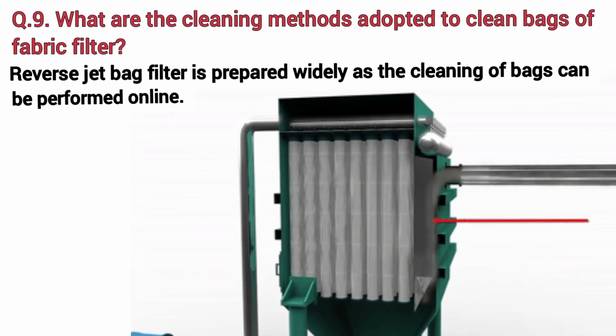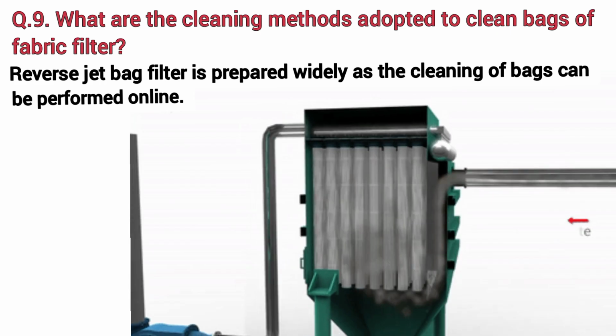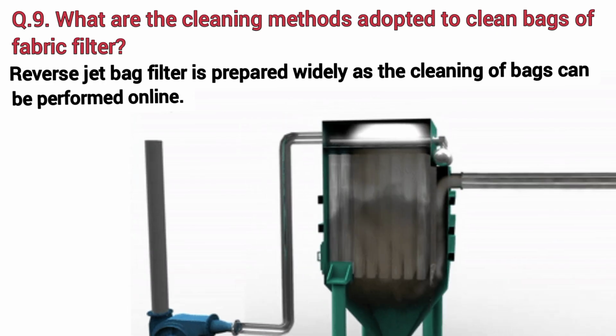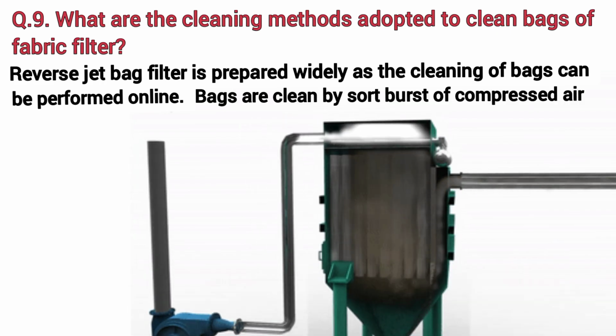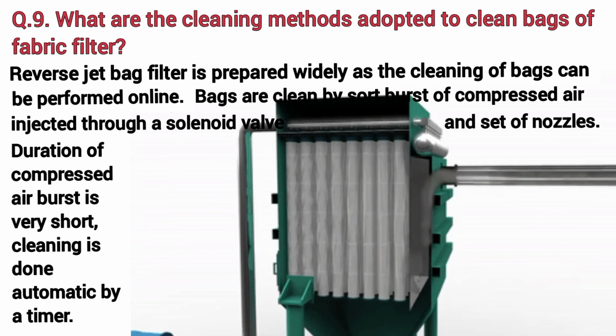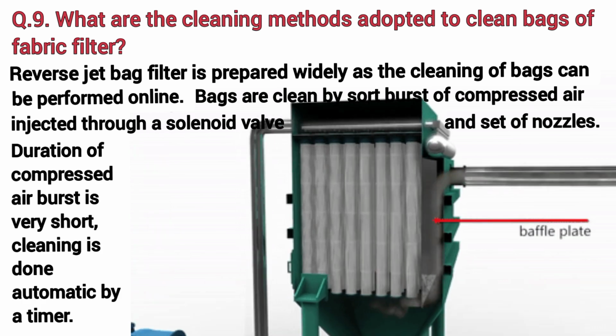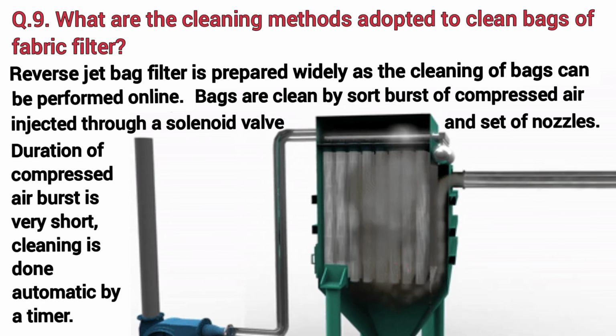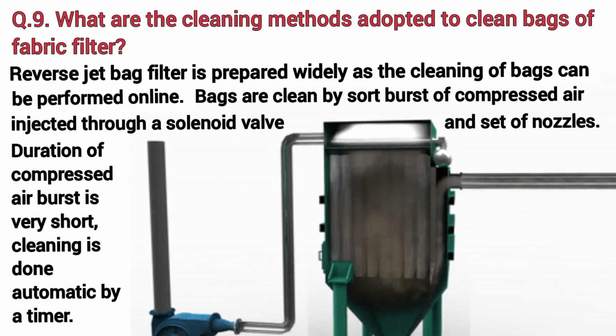Reverse jet bag filter is preferred widely as the cleaning of bags can be performed online. Bags are cleaned by short burst of compressed air, injected through a solenoid valve and set of nozzles. Duration of compressed air burst is very short. Cleaning is done automatically by a timer.